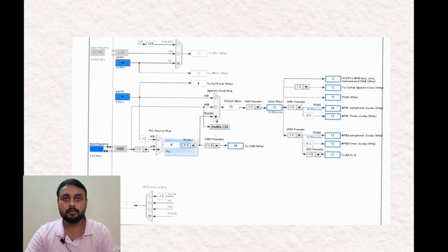So we have a base clock. You need to enable the overall system clock. You need to configure the system clock. Then for each peripheral, whether you want to use the port, the ADC, or the PWM, you need to enable the clock separately.